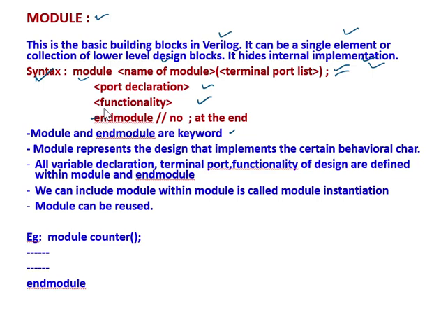All the variables that we use here we declare for our design, then the terminal ports we declare, and the functionality of the design is defined within module and endmodule. So inside module and endmodule I have the port declaration, then the functionality of the design.